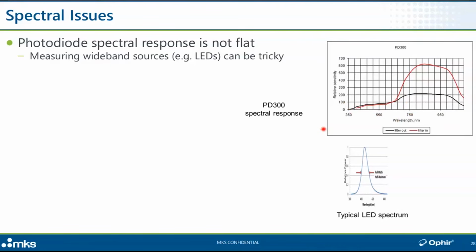Okay, now let's compare that to the spectral distribution of the light being emitted by a typical LED. I tried to place it in scale and in the correct relative position. So this is a blue LED, more like a blue LED. Typical spectral bandwidth here is going to be somewhere like 10 or 20 nanometers, full width, half maximum. So it's going to be over here.